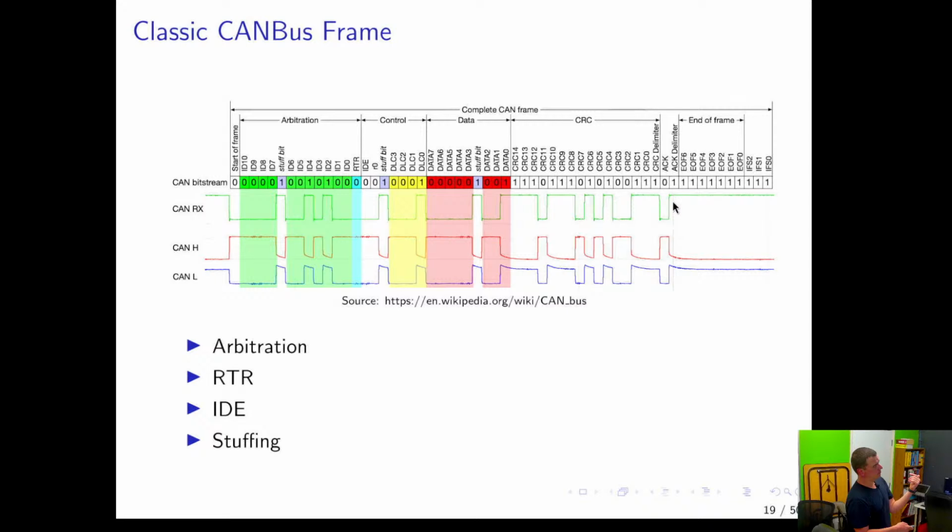All right, let me roll this back for a second. When you're sending data on the CAN bus, you're sending 1 bit at a time and monitoring the level of the bus. So you're like, I want to raise the bus. I'm going to get mixed up with the 2, but I'm going to raise the bus and check what the bus status is. And if the bus is lowered, that means somebody else is writing a different number on the bus, right?